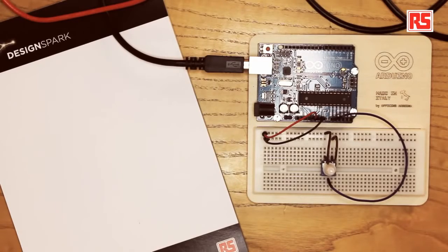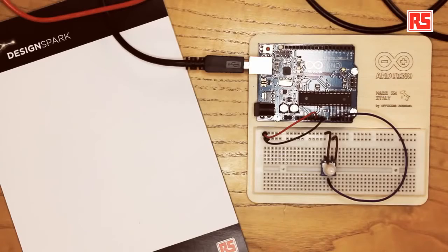There is a button on the Arduino IDE called Serial Monitor. If you press that, a small window opens up, and then you can see all the data that comes from the Arduino board visualized scrolling down the small window. And then there is a little menu at the bottom that says normally 9600, and that's, for example, the speed of communication used by the Arduino to send the data. So the Arduino speed of sending and the Arduino IDE speed of receiving have to be the same in order to keep the data readable.